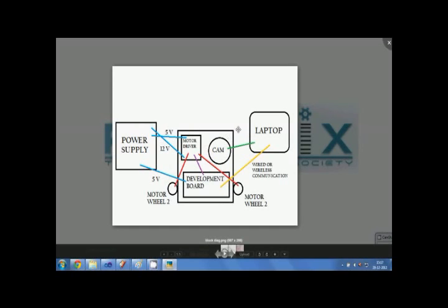So here is the chassis, just a symbolic representation. Here are the wheels. On the chassis, probably you would have the development board, which would contain the microcontroller. You'd have the motor driver, you'd have the camera, and the camera would be connected to the laptop. Now the laptop, you might keep it on the chassis if it's really large, but then even if it's not, fear not, we'll be having USB extender cables, so you can easily connect your camera to your laptop while you can sit comfortably outside the arena and let the robot move with the camera on it.